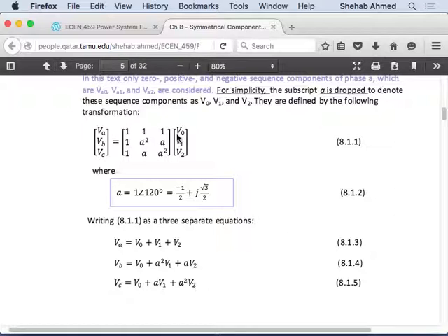If I find that my positive and negative sequence components of current are equal and opposite, I will know that it's a line-to-line fault. Line-to-line to ground fault, sorry. We will differentiate between them when we look at the numbers in more detail. But what I'm trying to say is that, at least for now, for the zero sequence, we have an appreciation for the fact that if I have zero sequence, there is something flowing in my neutral.